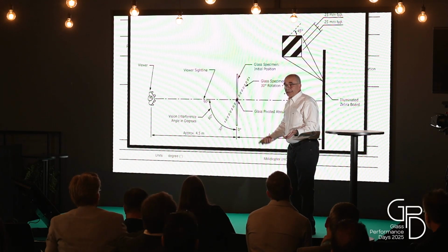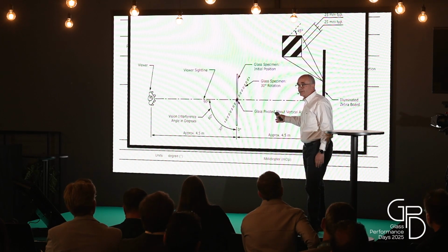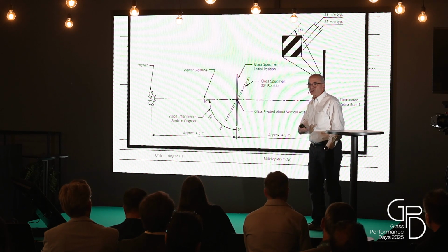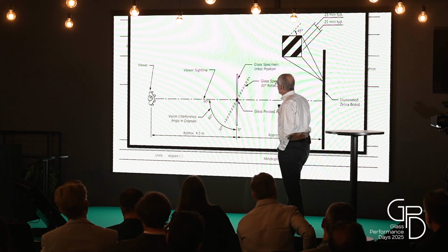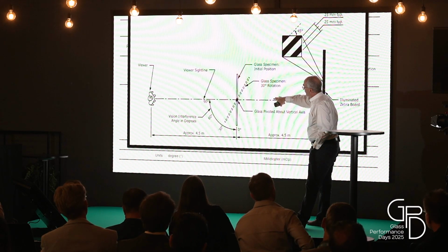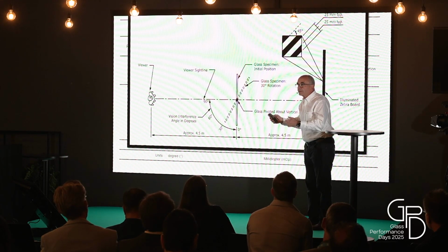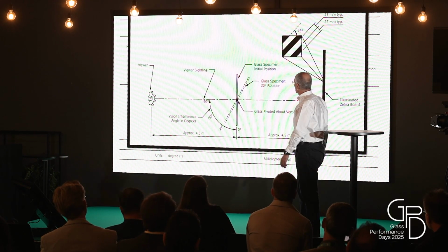Now, in our world, in the architectural world, we have the C1036, which is basically done for float glass, but you can use that on a finished product also. I've done it many times. So here, the observer is 9 meters away from a zebra board and looks through the piece of glass and rotates it until he sees the distortion.